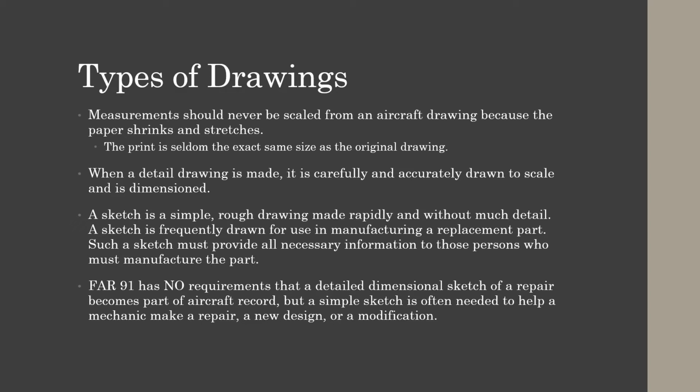Types of drawings. Measurements should never be scaled from the aircraft drawing because the paper does shrink and stretch during the printing process. So the print is seldom the exact size as your original drawing. When a detailed drawing is made, it is carefully and accurately drawn to scale and dimensioned. A sketch is a simple rough drawing made rapidly without much detail.